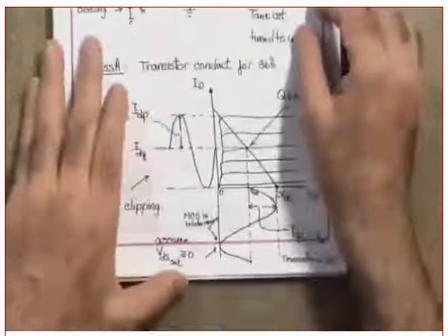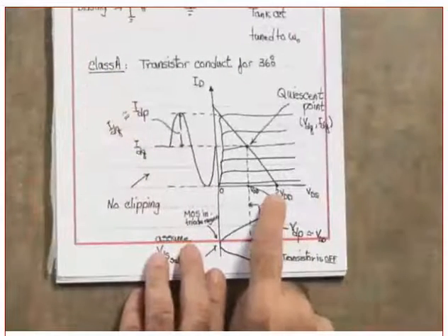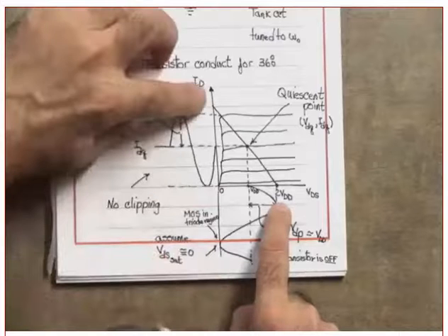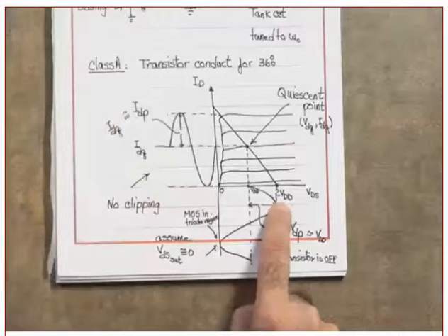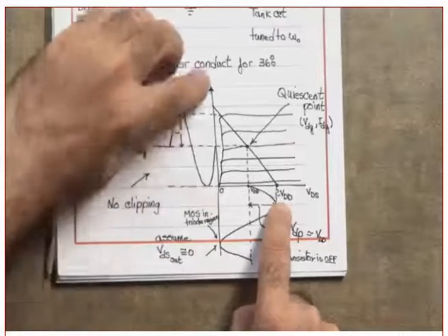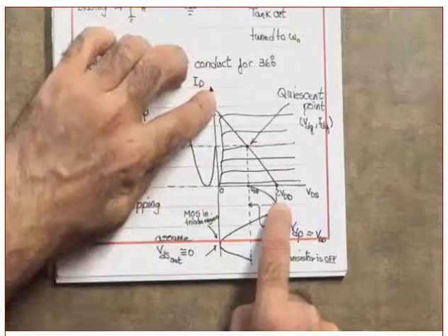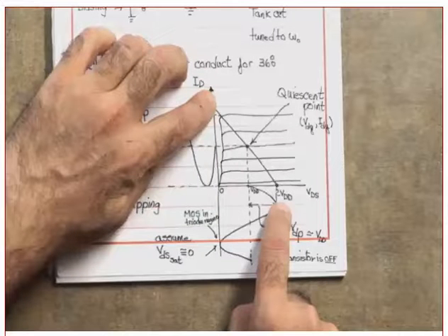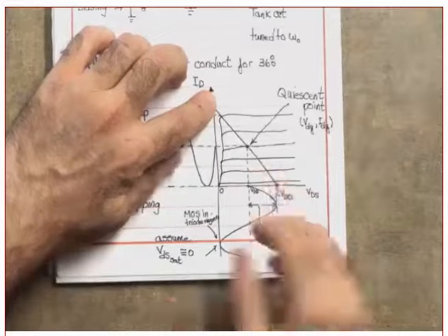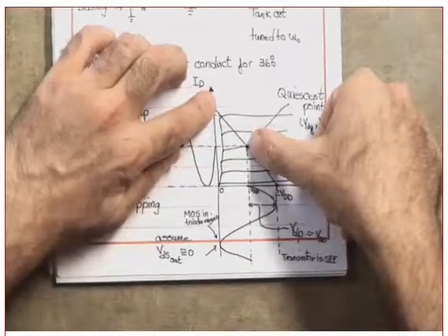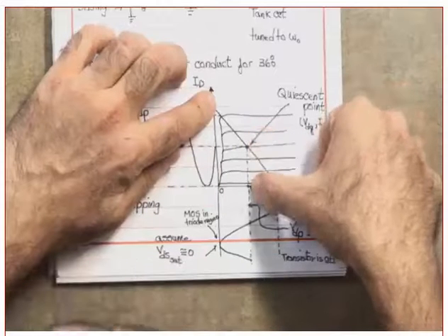Clear? Okay, good. Now, what is the maximum voltage that it can reach? VDS to VDD. Yes? This one here is VDD divided by RL. Are you following me or not? This is the maximum current. Where am I going to bias my transistor in a class A? This is class A. I'm going to bias my transistor in the middle of the load line, which means what?